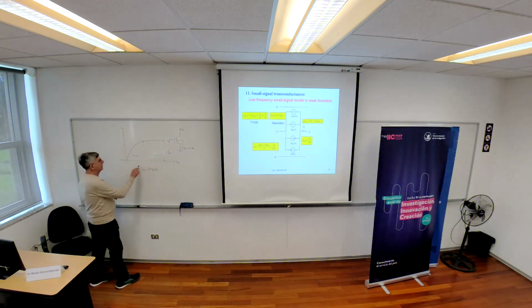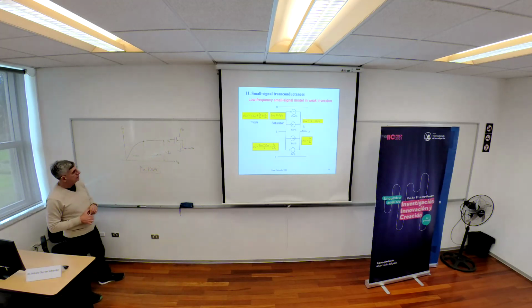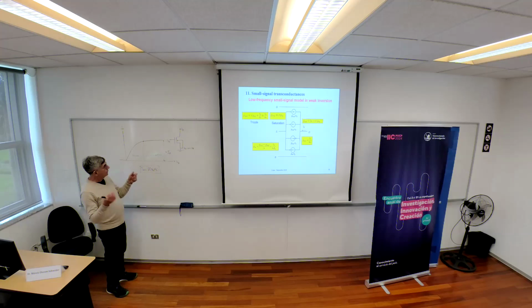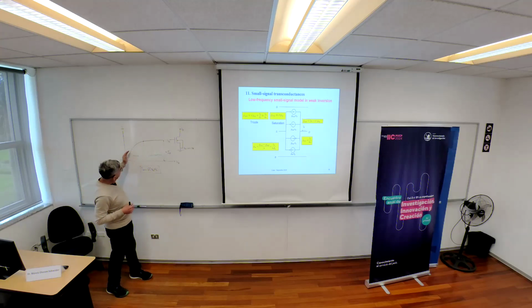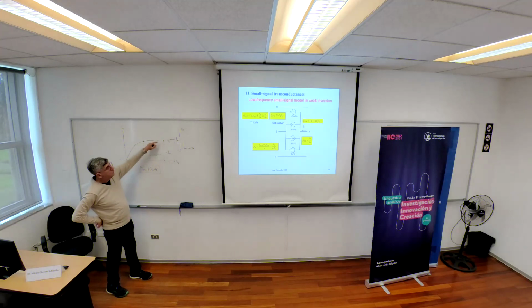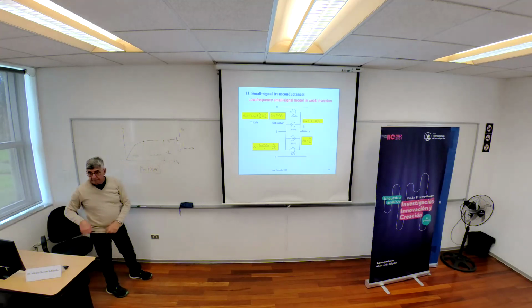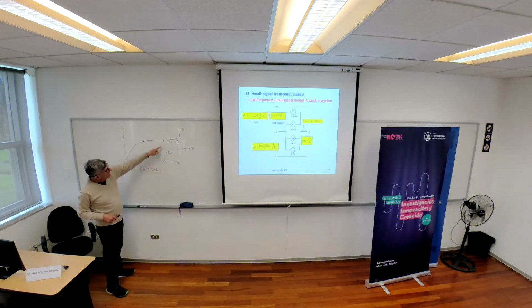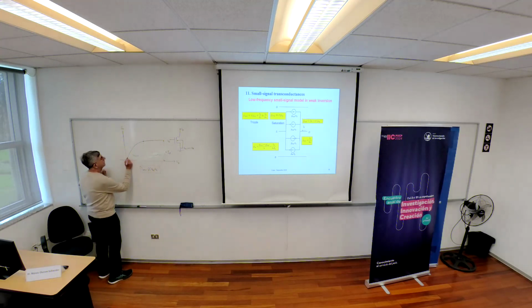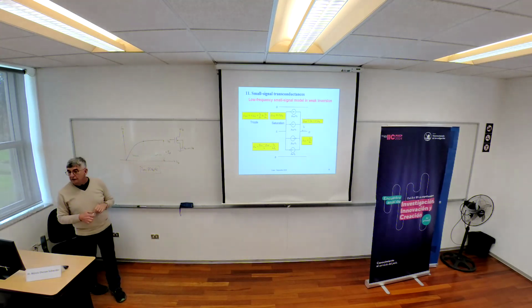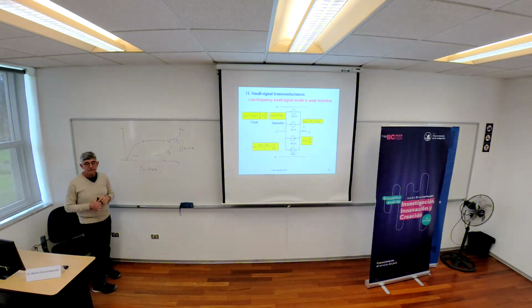Okay, so you know that IF is a function of VG and VS. And as I told you before, when you have a curve like this, you can infer the value of IF from this figure, okay? So IF at this point or IF here is the same. What happens when VDS equals 0? Both IF and IR have exactly the same value. Okay.